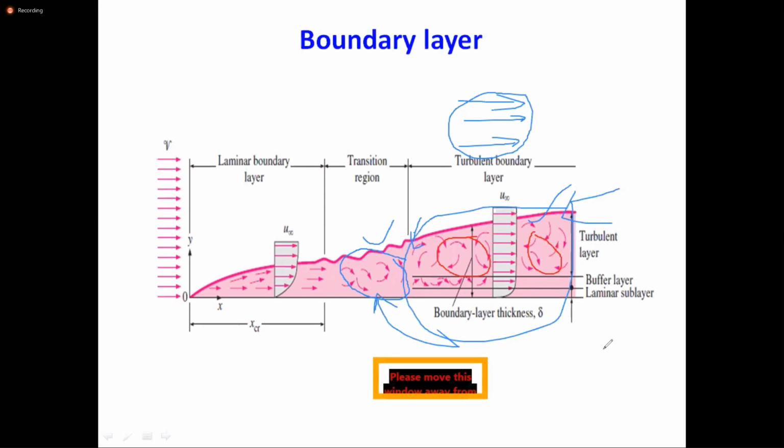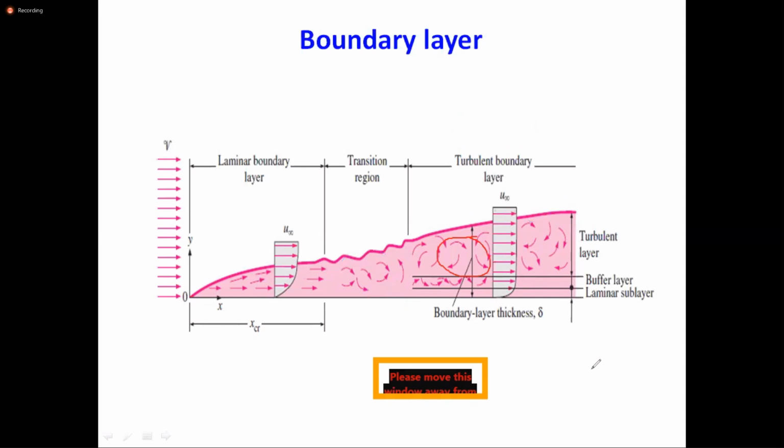In an open system there are disadvantages, but in a closed system, for example an IC engine, you talk about turbulence. Turbulence means you have to create it, so that it mixes the air and fuel properly. When it mixes, that means a premixed homogeneous mixture. If you give a small spark, it burns. So we cannot always say that turbulence is good. In an open system turbulence is a disadvantage, and in a closed system turbulence could give good efficiency.